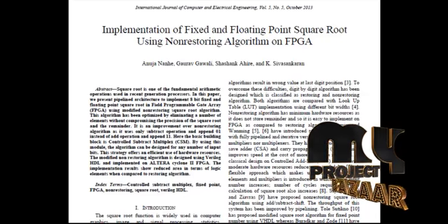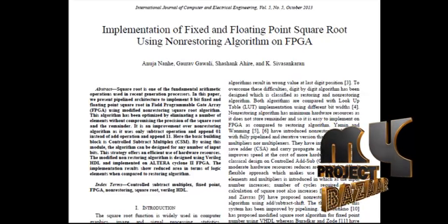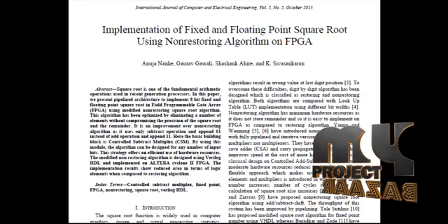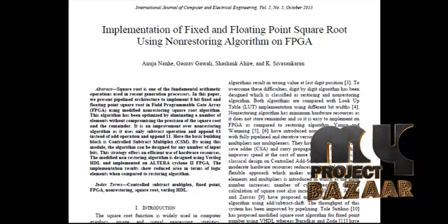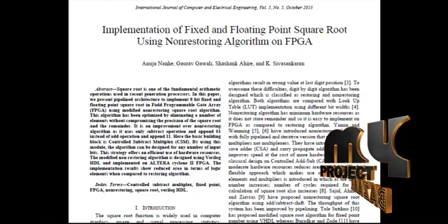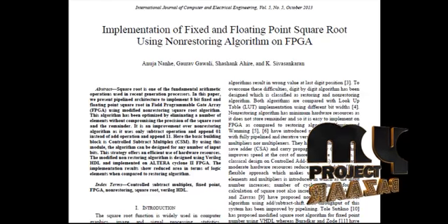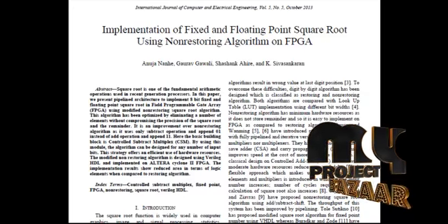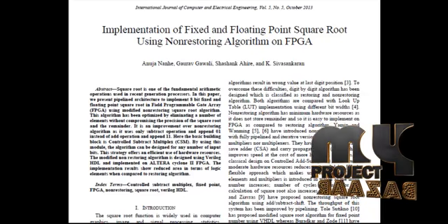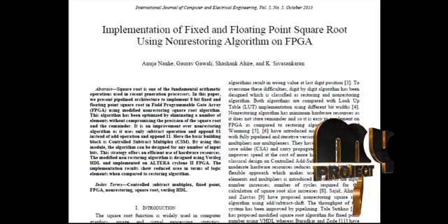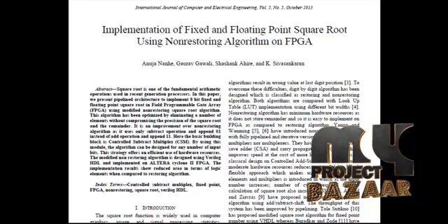Increasingly, scientists are interested in variable precision fixed and floating point operations, not limited to single or double precision operations, on FPGAs, in order to make those operations more resource efficient and more suited to their own applications. Among those operations, the square root can differ based on the algorithm implementation, and it can highly affect the total running time of the application.